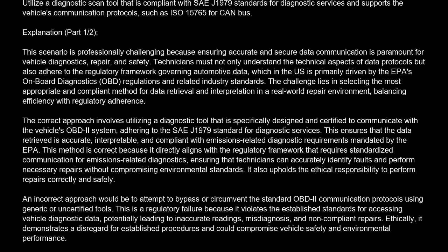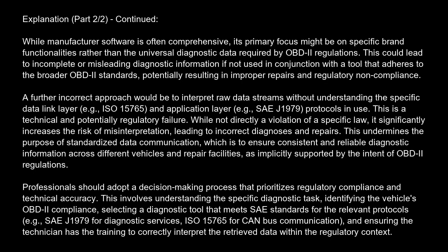Another incorrect approach would be to rely solely on manufacturer-specific proprietary diagnostic software without verifying its compatibility with the vehicle's OBD-II compliance for general diagnostic purposes. While manufacturer software is often comprehensive, its primary focus might be on specific brand functionalities rather than the universal diagnostic data required by OBD-II regulations. This could lead to incomplete or misleading diagnostic information if not used in conjunction with a tool that adheres to the broader OBD-II standards, potentially resulting in improper repairs and regulatory noncompliance.